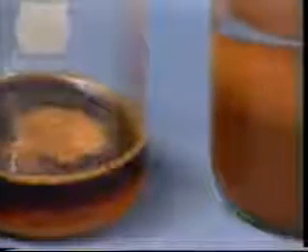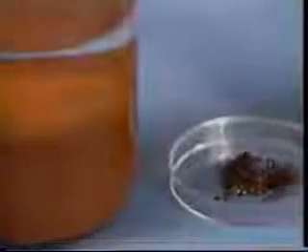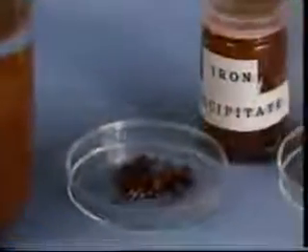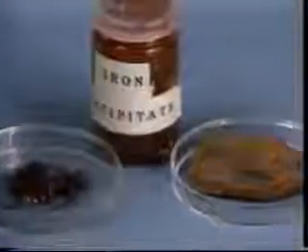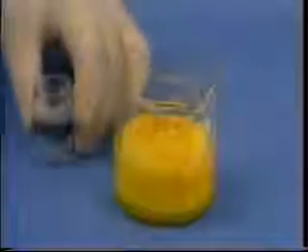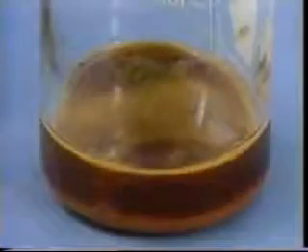The notable exception occurs when HCl contacts iron, usually in the form of the tubulars. Iron is dissolved in the acid and then carried into the formation. There, the iron-bearing acid reacts with the carbonate material. pH increases, and ferric iron, which can plug the formation, is precipitated.